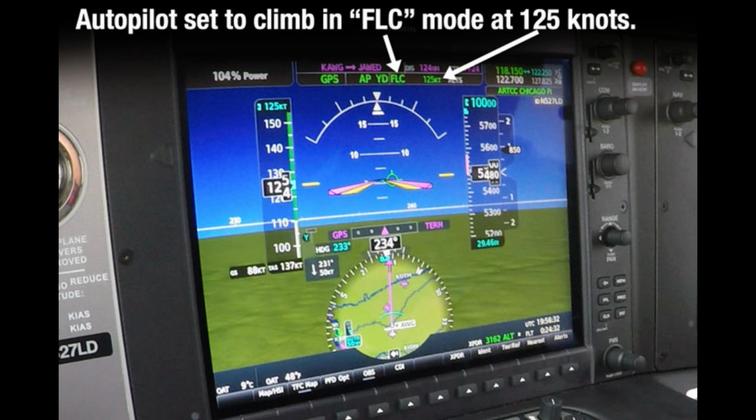Determine if engaging the autopilot cancels certain FD modes. Some units interact, and when the autopilot is engaged, some FD modes are automatically cancelled, notably altitude hold or selection.